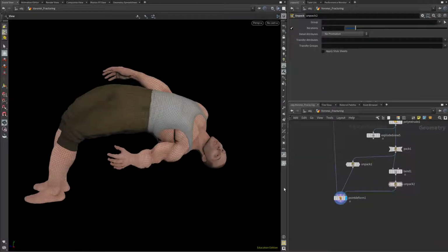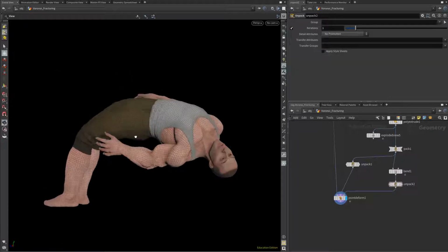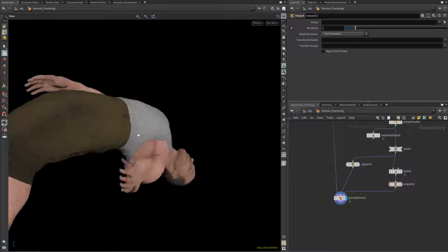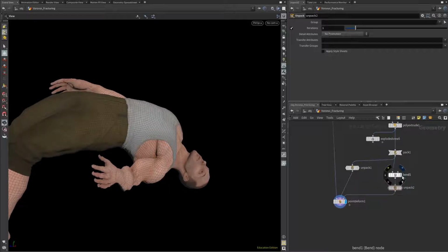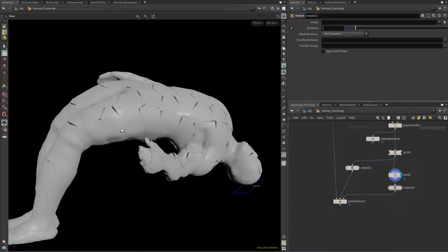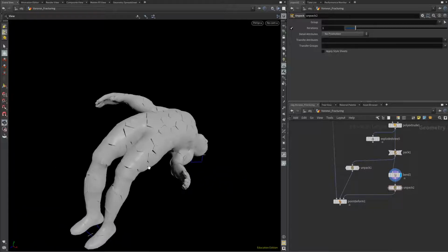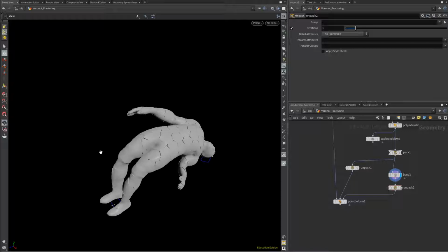You can also use the same principle in reverse, where perhaps you have a deforming character like this animated in your shot, and you need some proxy pieces to use as colliders. As you'll find out later, it's not really good to just use the character as one mesh as a collision object for a rigid body simulation.